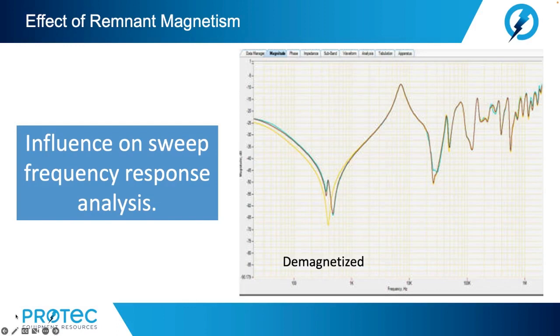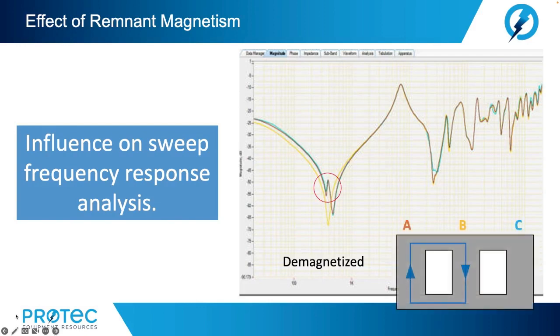Two significant parallel and series resonant points can clearly be seen on the outer windings. This can be attributed to the two magnetic paths with different lengths. Here we see the first resonance and equivalent magnetic path. And here we see the second. In comparison with this, the winding on the middle limb displays only one characteristic single resonant point.